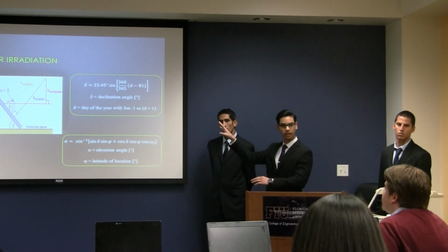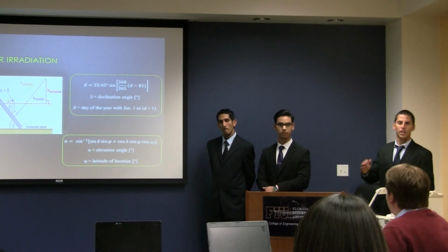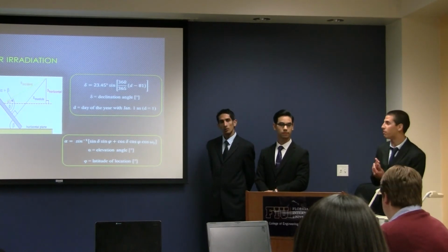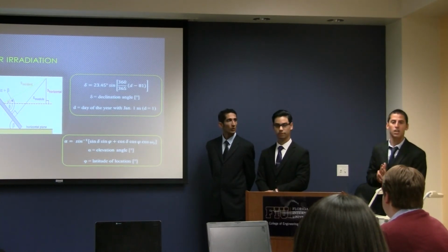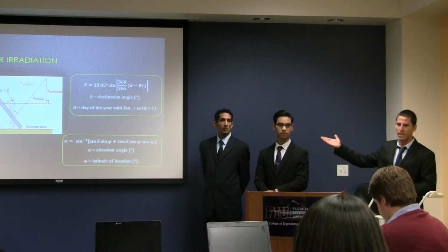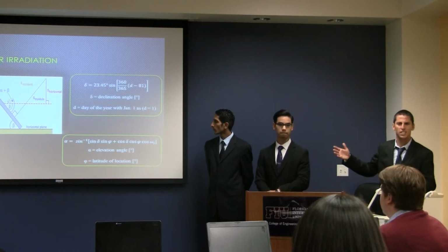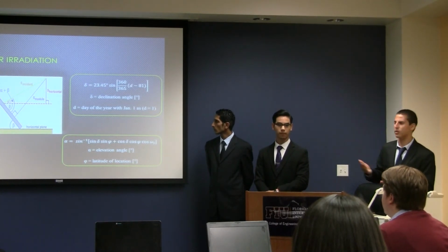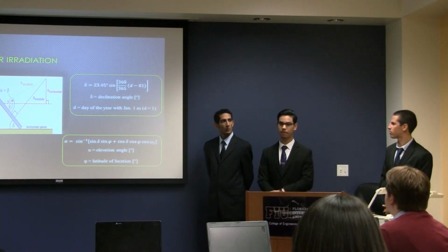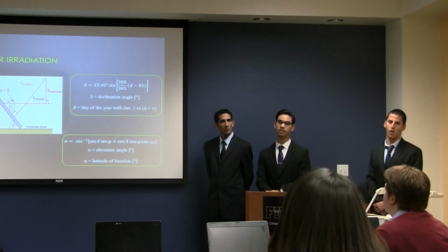It seems to me that if you're going to predict based on this curvature, you want to incorporate all of that. That's why we need to calculate the irradiation and efficiency ratio for each cell for the panel. Each cell is going to be different with different angles. Our table shows different angles for one of the cells we use, just an example calculation, because we can't put every calculation in the table. I understand. It's actually different every minute. Every minute it's very different. It's not the same thing.